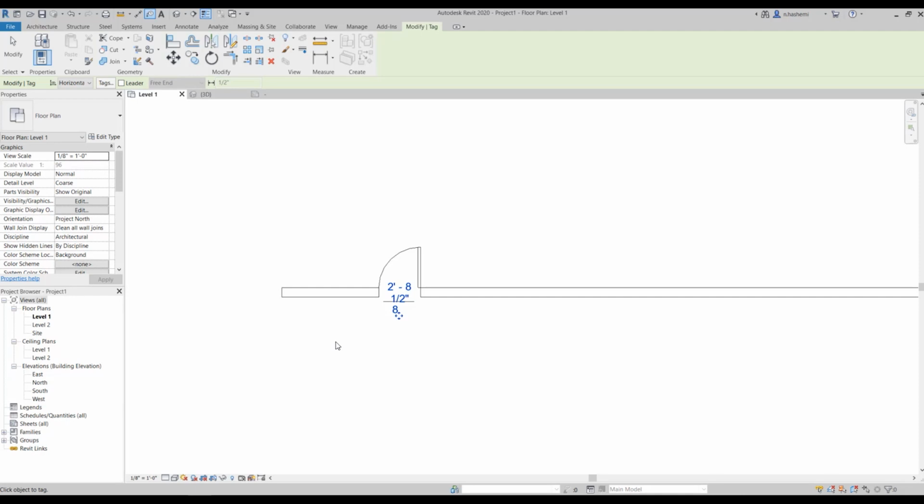The next topic that I'm going to talk about is something that might be new to you. So we want to see how we can model something from scratch in Revit. For example, we may want to design a custom bench or custom light fixture or any other thing. And you can create all of those just by using some kind of extrusion in Revit. So let me show you some examples here.